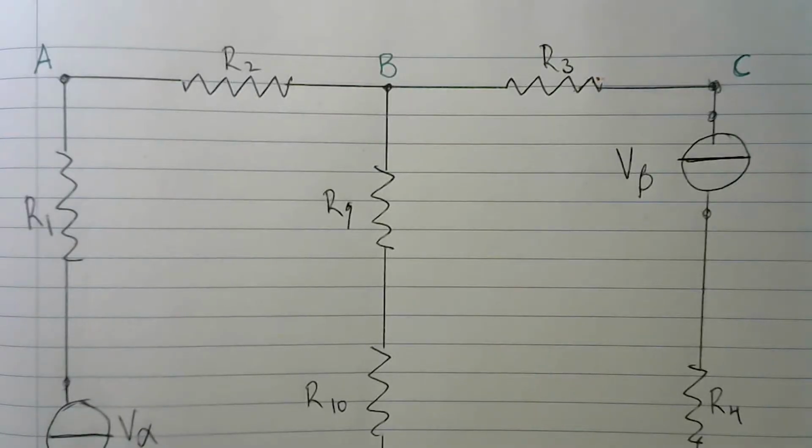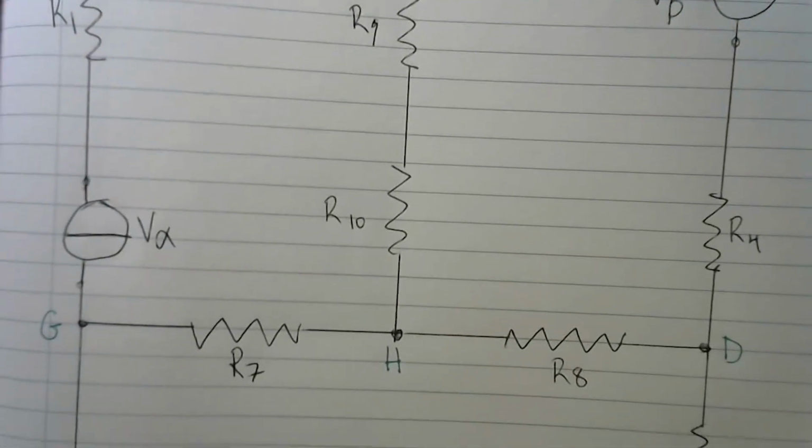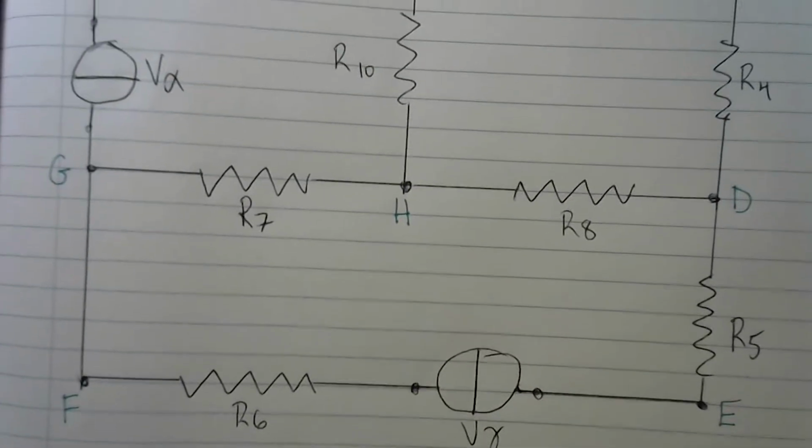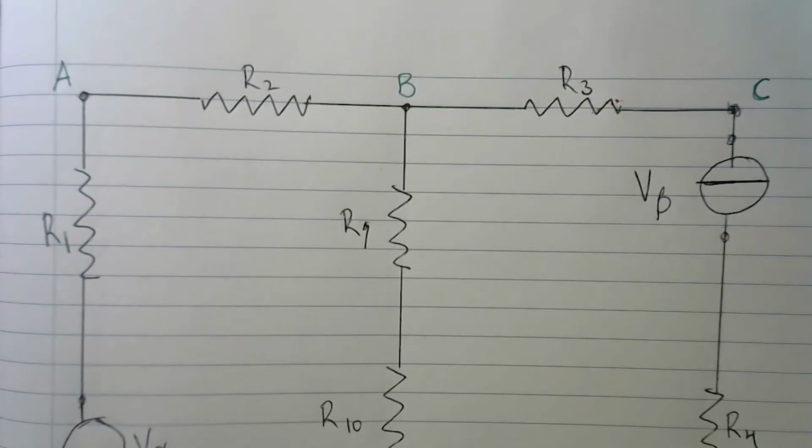Now, when analyzing our complex circuit, we want to use our Kirchhoff loop and junction rules. And I do not have a printer, so I made a hand-drawn version of the large circuit diagram. So the whole thing is here, but I can only show part of it at a time. So to begin, normally the first thing we'd want to do is choose a direction for the conventional current, because we would not know which way the current is flowing. So the correct method is actually just to guess and then see if you're right at the end.